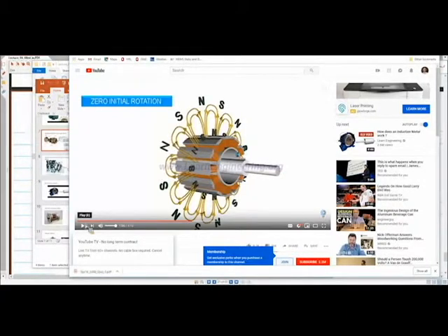So we went through a pretty lengthy discussion about three-phase power and how this translates to coil energization in a three-phase motor. We showed a very simplified case with just two poles, north and south, so a single coil for each phase. This is what an actual AC synchronous motor would look like, where instead of just a pair of poles, we have a multitude of them.